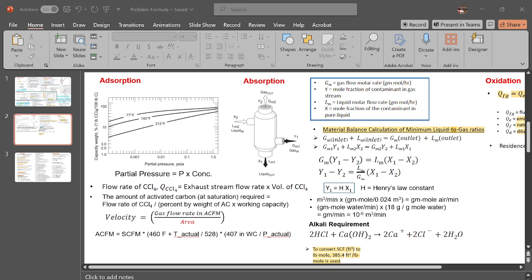Yeah, they have given the flow, they have given the velocity, each bag they have given, so you can find the area of one bag and the area to cloth ratio. Is there anything? No. So they are asking the number of bags required.